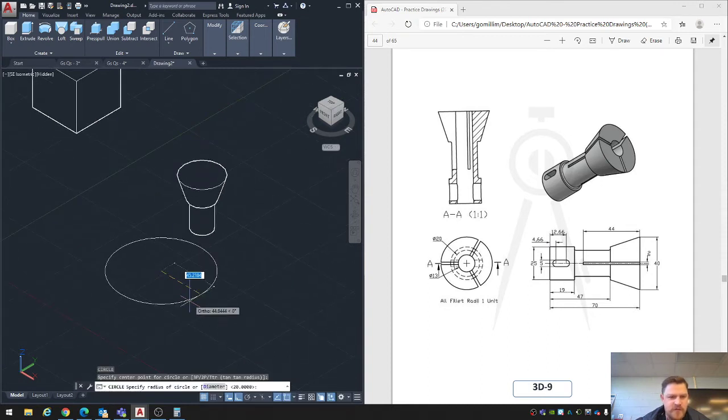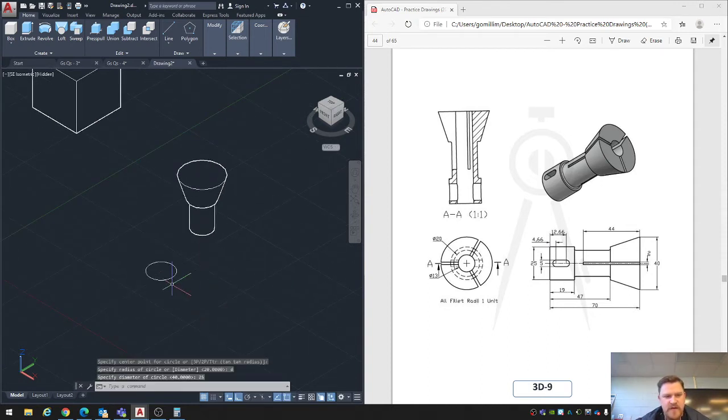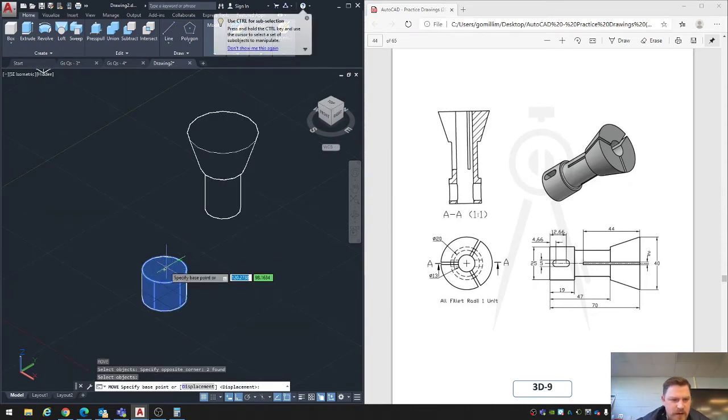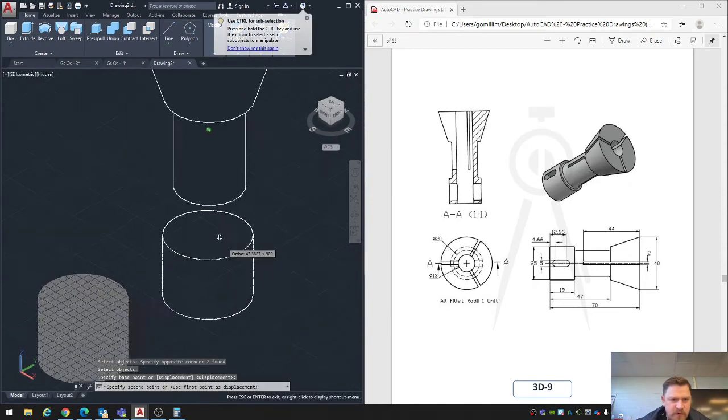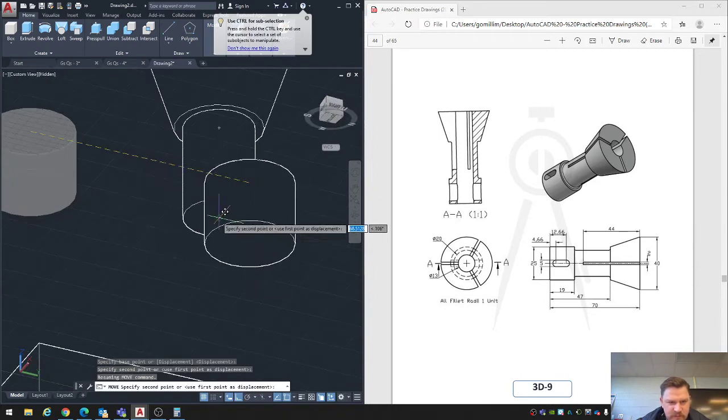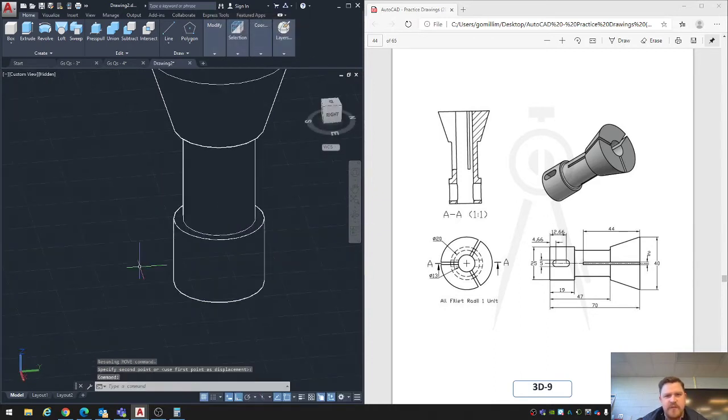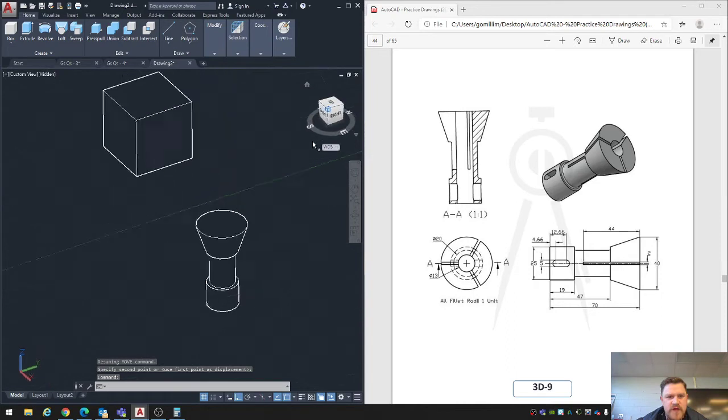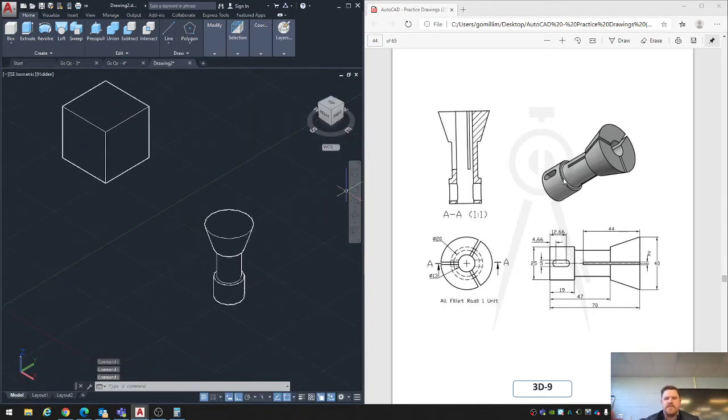Diameter circle. So I'm going to do circle, diameter 25, and press pull that down 19. So now I've got that piece. And then I can press pull or move that by grabbing it at the middle or the center, and then I can move that to there. So that is kind of the object so far.